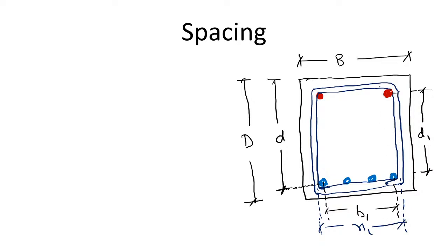And so guys, in this chapter, detailing is very important. Unless you fix the diameter of the steel, size of the stirrups and all, you will not be able to calculate all these things. So how can you remember? This B1 and D1 are similar things. B1 is in the horizontal direction and D1 is in the vertical direction. It is the center to center distance of the extreme reinforcement. And what about x1 and y1? It is the distance between the center of the vertical stirrup on one side to the center of the vertical stirrup on the other side. Okay.